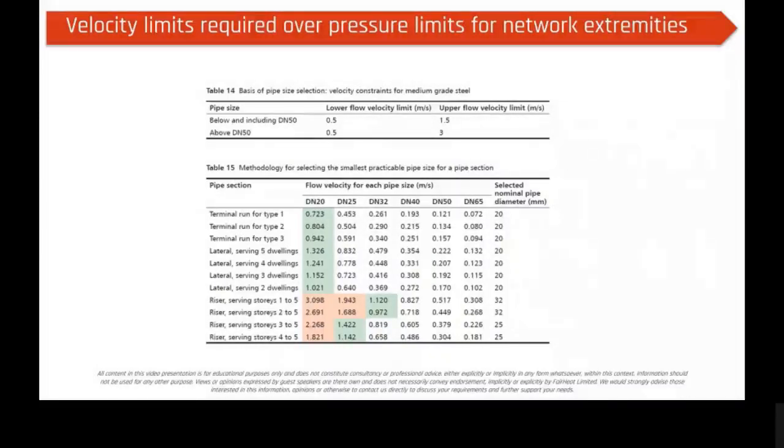But what you really need to do is a life cycle assessment of how to optimize my sizing of pipework in terms of reducing losses, versus not resulting in a way oversized system that also has extremely high parasitic loads that are offsetting those heat losses. So really big steps for CP1, and we should start seeing a lot more appropriately sized network distribution systems that will drive down losses significantly. But there's an optimization piece to be done at RIBA 3 and RIBA 4.